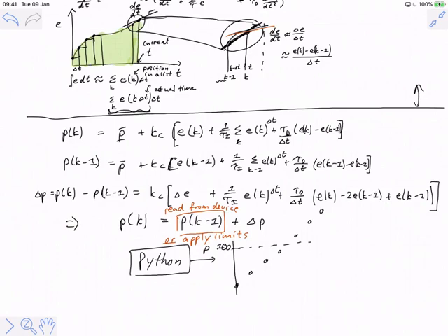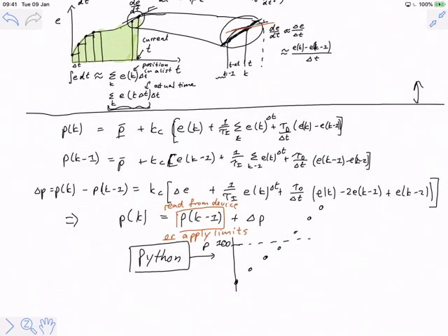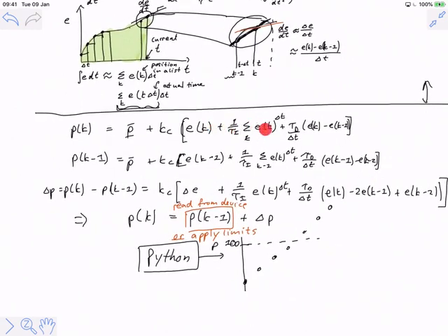Once the output isn't saturated, start integrating. The difference, of course, is that that requires some logic. So we have to have an if here that does the integral conditionally.